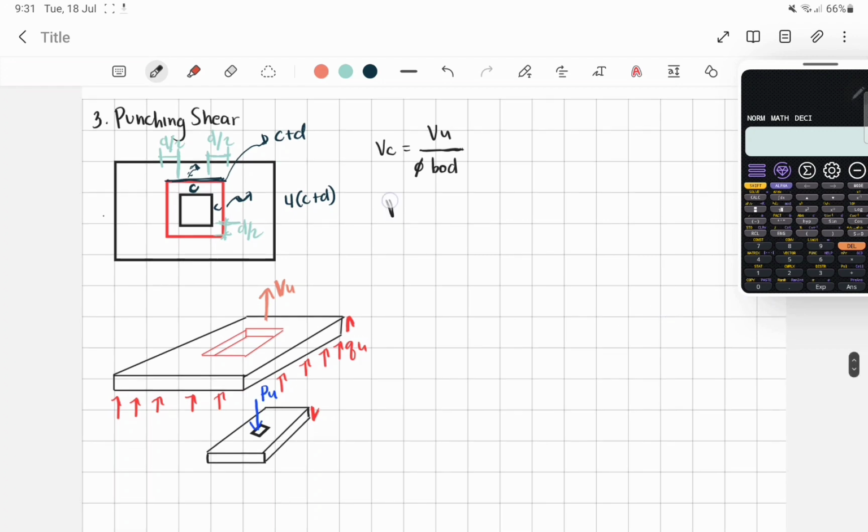To get the shearing force, we have to consider a member. Any member of the two, we can use. They are equal. For this problem, I will use this one. Then maybe I'll also explain how to get the shearing force of the lower part, the portion that was punched through. What is the shearing force there? This is the shearing force, and the shearing area will be this.